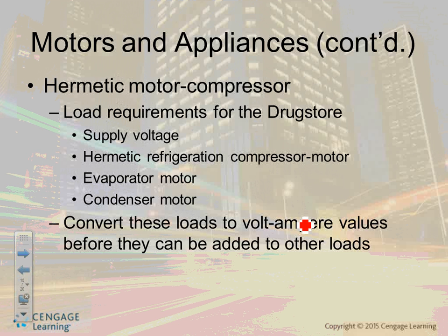And the inside, gentlemen, it comes to the evaporator. The evaporator has a blower inside it. The same thing. It takes the air in your house and circulates it through these coils. They call them the coils. It collects the heat. The heat transfers from the air to the coils, from the coils to the refrigerant inside them, and they shove it all the way back to the compressor. They compress it, and they have a big blower outside that blows the heat out, and they keep doing it over and over again. And again, we'll do that one in industrial, guys. We have a whole lot of stuff about it.